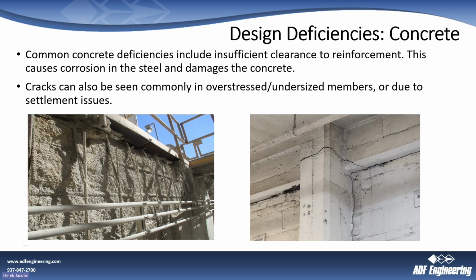Cracks, like this large one here in this column, can be caused by a couple different things. It could be overstressed or undersized members, or some sort of settlement issue with the foundation. So we can kind of show here.